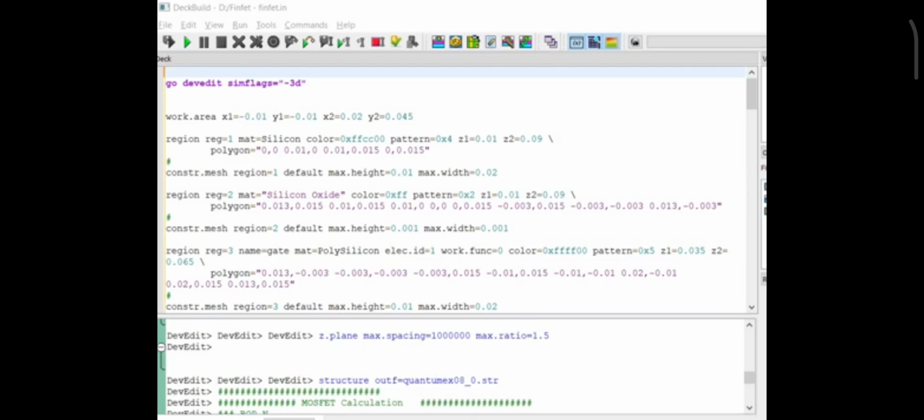There is a difference between a Silvaco standard file and a DevEdit file. In the case of a Silvaco standard file, a mesh describes the device and after that a region is defined with material. In case of DevEdit, a DevEdit file contains the DevEdit cards needed to create a device, the analytical impurity functions, mesh creation, and DevEdit mode settings. To start DevEdit, enter go devedit in the terminal window. This starts DevEdit in the graphical user interface mode, as opposed to the batch mode.